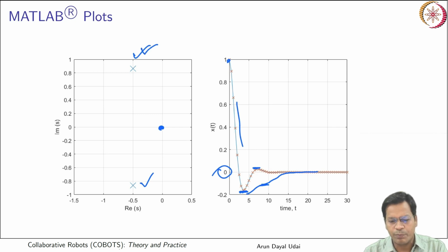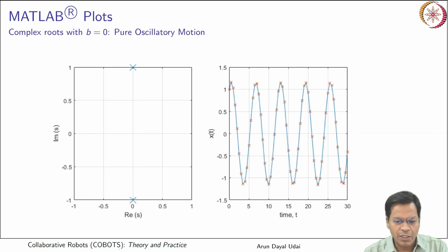So this time you have poles which are on the complex side of it. You have these two complex values, and they are on the negative side of the complex plane. So negative real part and complex conjugates: the system has damped oscillatory behavior. Okay, now let us look at the system when it was an undamped system.